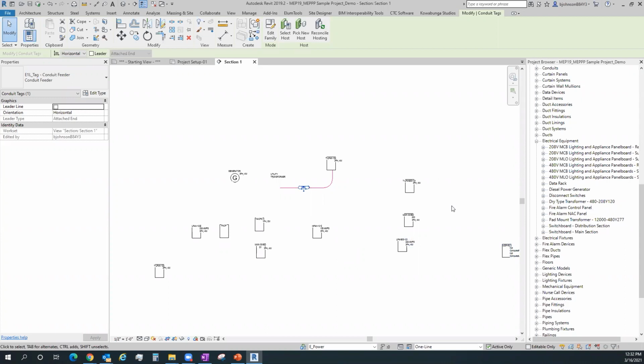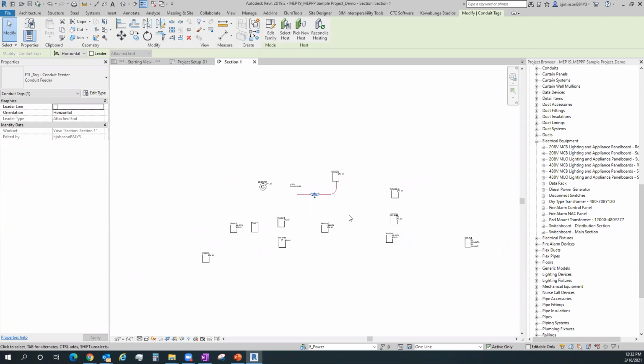So while this isn't a super fully fledged, best case ever one-line scenario, the concept is very strong. So I really like that about how the pack is giving people that aren't using high-end analysis software for electrical the ability to do a one line and track it with real objects. Let's see, what else do we have here? And again, your vendor families that you may have in there, all you would need to do is make sure that those vendor families have the right parameter embedded in them.